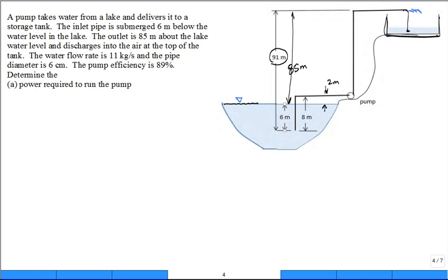So now the water level is full up here. True? And then something happens. Somebody shuts the pump off, but somehow it's able to flow backwards through a centrifugal pump that's just sitting there. The passageways are open. The pump used to run and sling it out and throw it around. That's how the pump worked. It actually could be a siphon. The water could suck back out, go through the pump, spin it a little bit, and you'd come back the next day and your tank would be empty. That's why they don't do that.